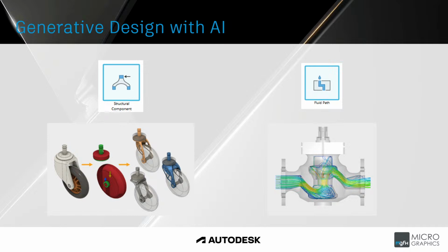And so we'll go through the steps in generative design. We can see the second step there with the yellow and the red geometry, the green and the red geometry, that is showing the areas to shaft that will hold the bearings. And what generative design will do is it will create geometry to connect to those areas, but that geometry is created to withstand the forces that would be applied to the wheel. So you set this wheel up with fixing constraints and forces so that the software has a starting point to start calculating how much material is required.